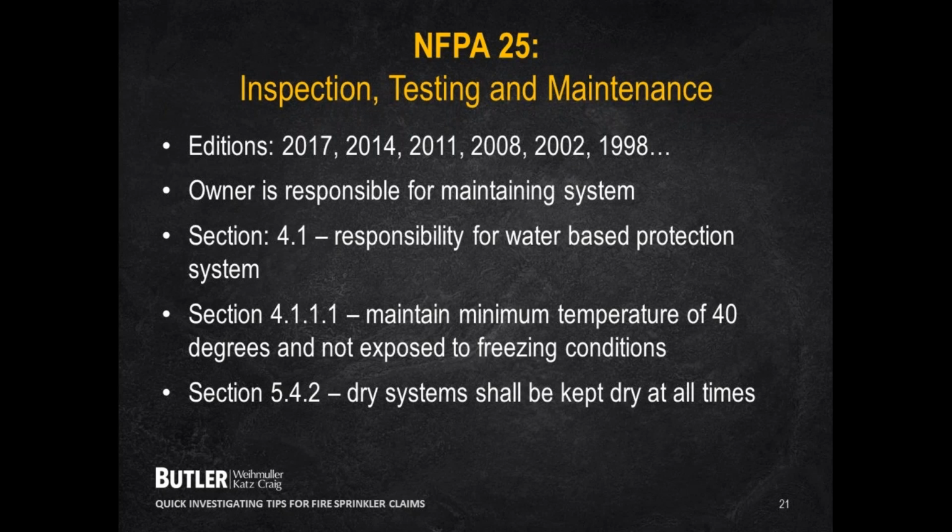Let's see here. Those are more of the different NFPA provisions on this slide. It goes over the section about maintaining the minimum temperature of 40 degrees and not being exposed to freezing conditions. And there's that last NFPA provision that you'll see over again: dry systems shall be kept dry at all times.